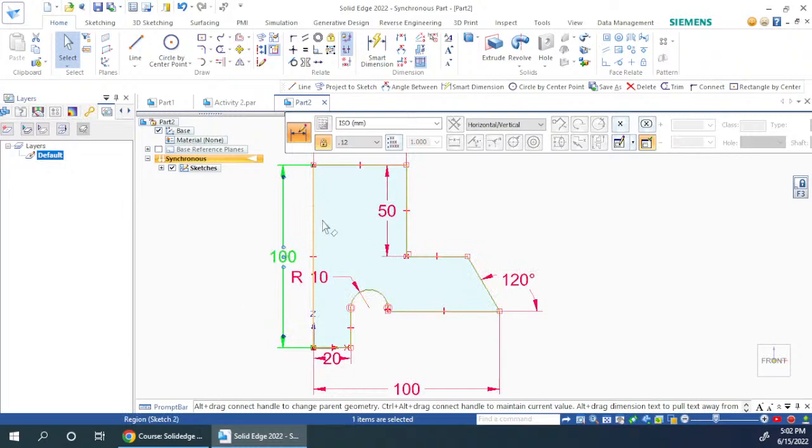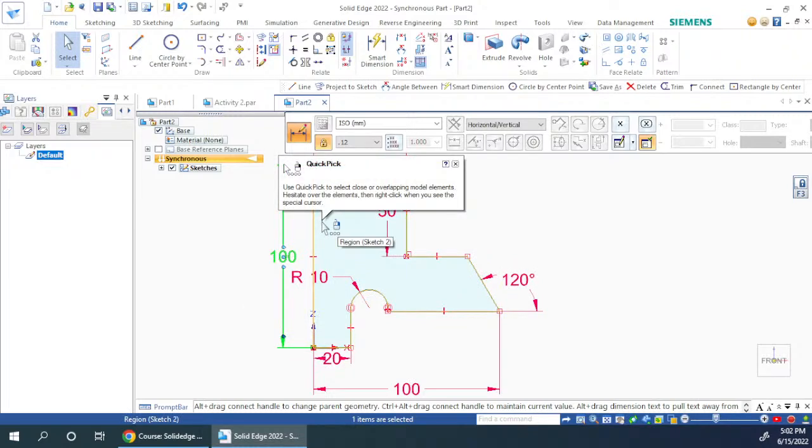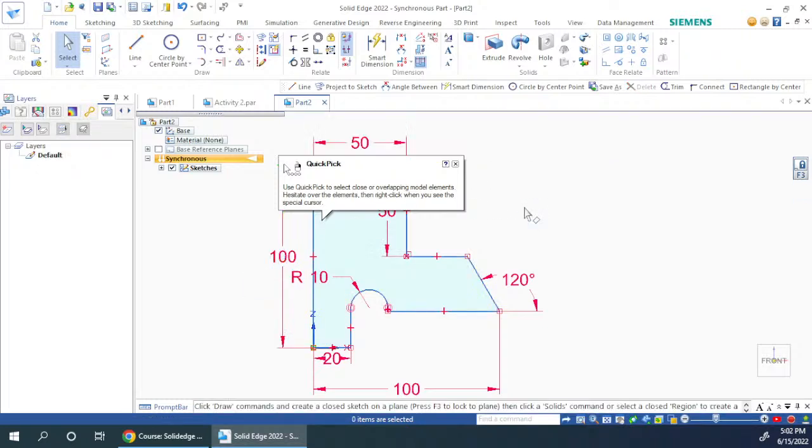Fine. So horizontal. Yeah, of course. Now, right, I changed it after opening it. Okay, so whatever is the length, you apply it, and after applying the length, please change it. Try to change it. When you change it, the relative constraints should not get modified. So for example, here now this has got modified, right? So it should not happen like this. So if that is happening, then you have to properly apply the constraint.